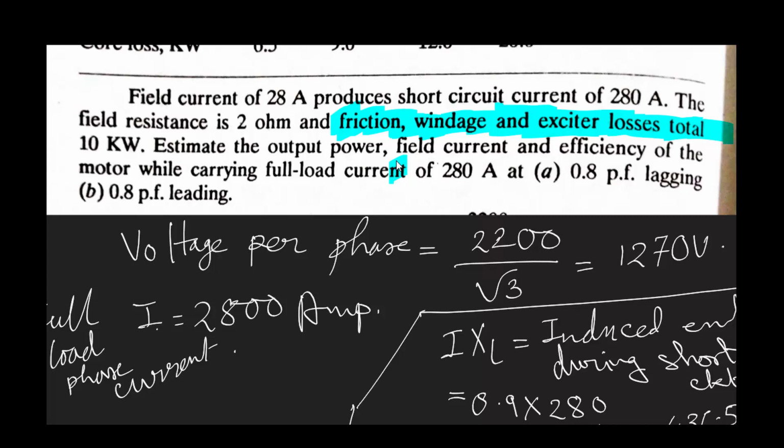So, therefore, in case of synchronous machine, core loss may vary, and core loss should not be clubbed with the other losses. In some cases, to avoid complication, we may club core loss with other synchronous losses, but generally, if possible, we should try to avoid it.